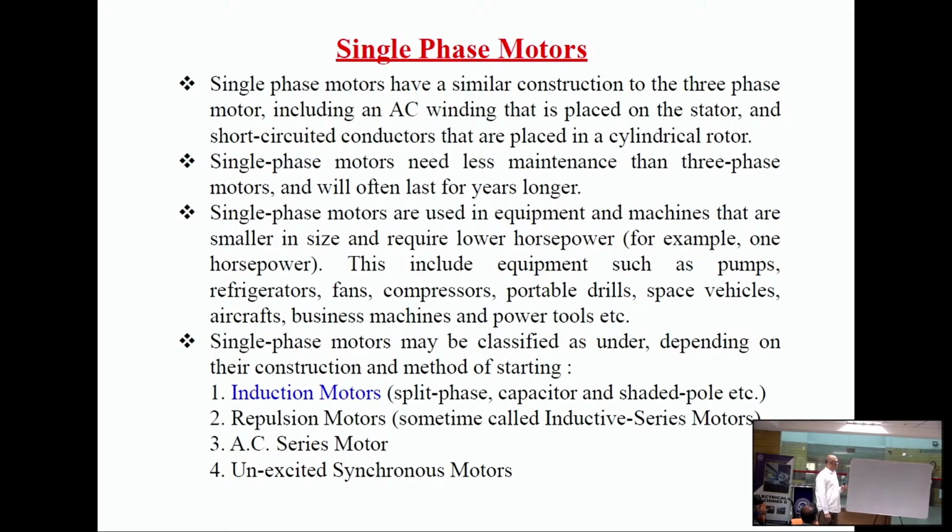Why are single phase motors used? They need less maintenance than three phase motors, and that's why they will last longer. This is true for small power. For high power machines, three phase is preferred. For small power, fractional kilowatt machines, single phase is preferred. Large industries use three phase induction motors. Single phase motors are used in equipment and machines that are smaller in size and require less horsepower, for example pumps, refrigerators, fans, compressors.